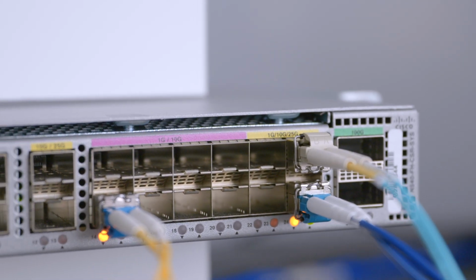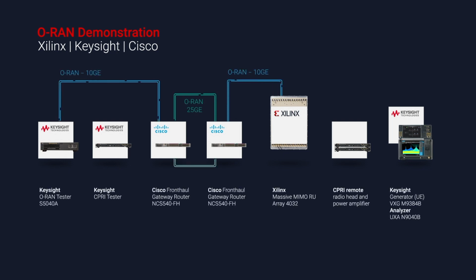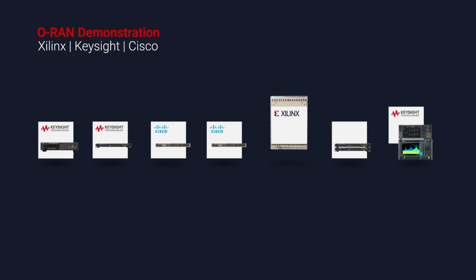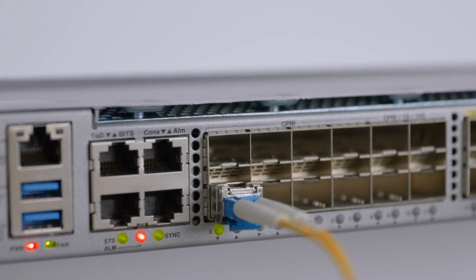In this application, the Keysight Open RAN Studio feeds 10 gigabit per second Ethernet traffic to the fronthaul gateway, which is then passed on a 25 gigabit per second Ethernet link to the second router, where it's converted back to 10 gigabit per second Ethernet and forwarded to an RU. This process is relatively simple as O-RAN is using Ethernet packets natively.